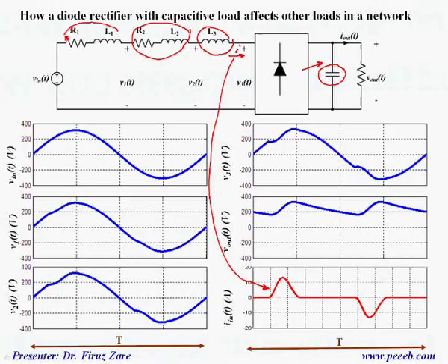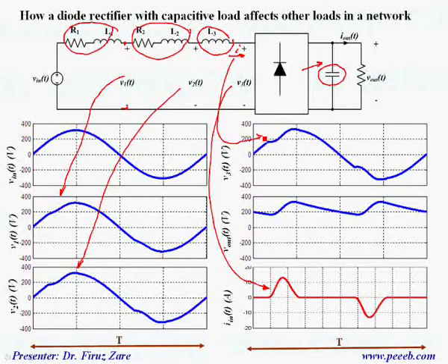That's why the voltage at these terminals is affected by these currents, which are not sine waves. So when we design a power converter, we should also consider the power quality. Especially for a high power converter, we need to comply with IEC standards and also control the input current harmonics.